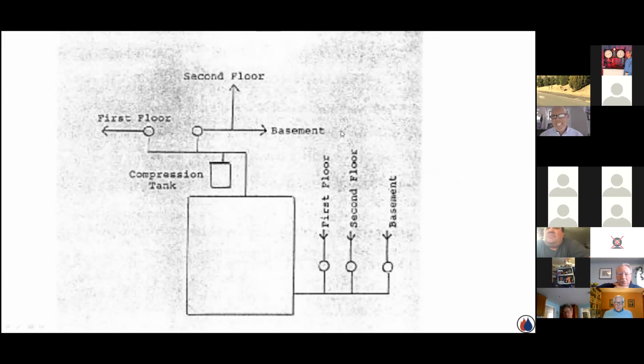Ever since he did that, there were times when the second floor just could not heat properly. It wouldn't get warm. And so he's out there trying to figure it out. So he makes this drawing and sends it to me, and we talk about it. And as we spend some time, this is another purpose of flow control valves. In addition to preventing that gravity flow, they also act as a check for reverse flow. And here's what I mean.